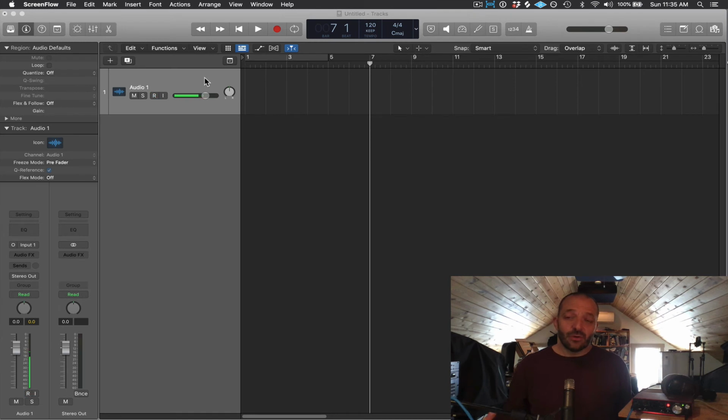Now we're ready to set our recording level by boosting the input gain on your audio interface and turning that gain knob to the right. Obviously I've gone through that process with the mic that I'm speaking into. As you're playing your instrument or speaking or singing, you want to be doing that at around the loudest volume that you would be recording at. So maybe that's singing or playing the loudest section of the song, which is possibly the chorus. Make sure too, if you're recording dialogue, that your speaker maintains a consistent distance from the mic. And for me right now, with this mic and in these surroundings, I'm getting a decent sound at about 8 to 9 inches from the mic.